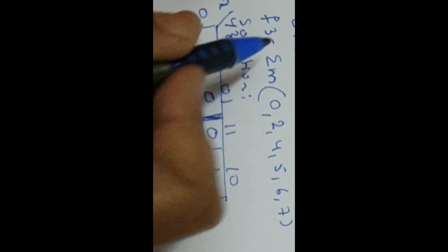Next on this line, if you fold again, all fall on one square. Hence these 1, 2, 3, 4 make only one group, that is a quad group. So that is grouped as the second quad. This is the second group. It is a quad having 4 members, 1, 2, 3, 4.